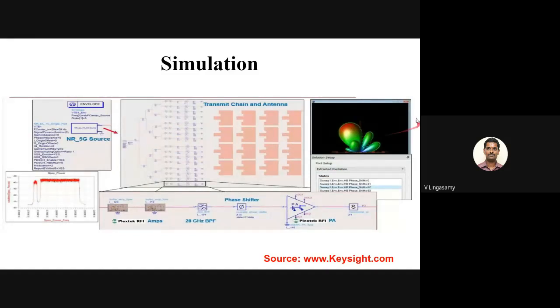Along with the beam sweeping, MATLAB has a physical layer 5G NR toolbox. So you can generate the signal from the toolbox and give it as an input to the RF transceiver chain. Then that will be fed to the array, and you will steer the beams. Based on the beam feedback and beam characteristics, you can feed these parameters as an input to MATLAB and simulate the UE in a particular direction, and then see what throughput and what signal level I'm getting. All that can be done.